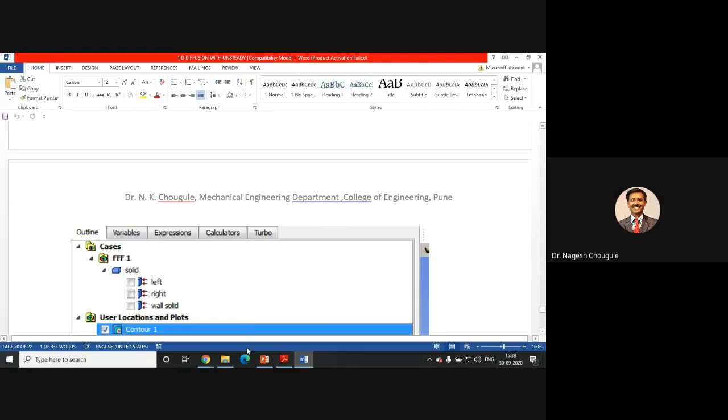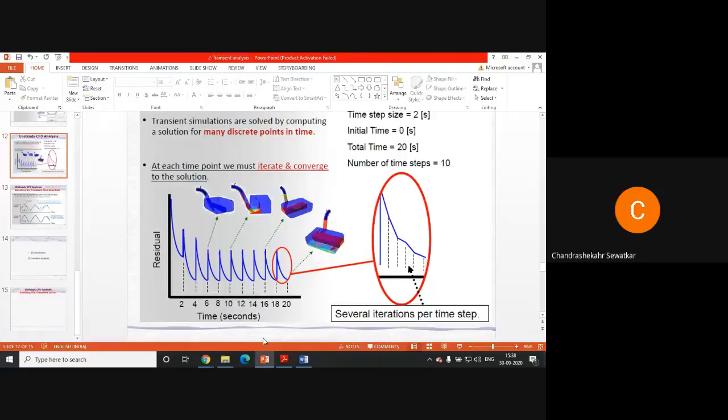Okay. There is another question. How can we reduce the iteration time if a larger number of elements are there? If the number of elements is higher, he says that the time is larger. Yes, it will take longer, definitely. Can we reduce that time by doing something else? Yes, you can use inflation, for example, for flow through a pipe.